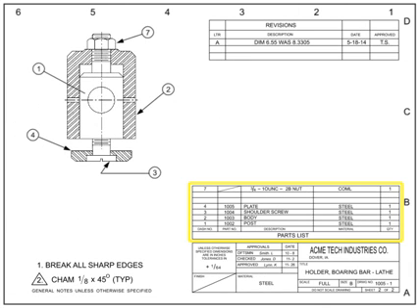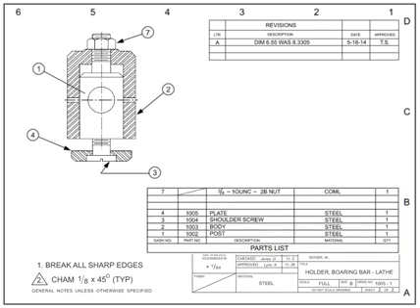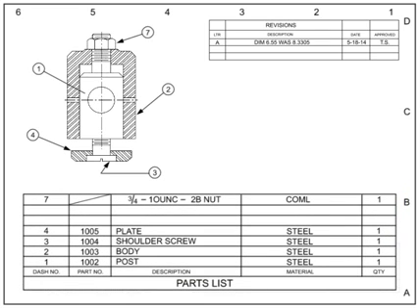The parts list, also called the bill of materials or list of materials, is a tabular list of raw materials or subassembly parts used to make an item. Used only on assembly drawings, parts lists are typically located directly above the title block. Although some drawing standards put the parts list on its own sheet or even as a separate document.